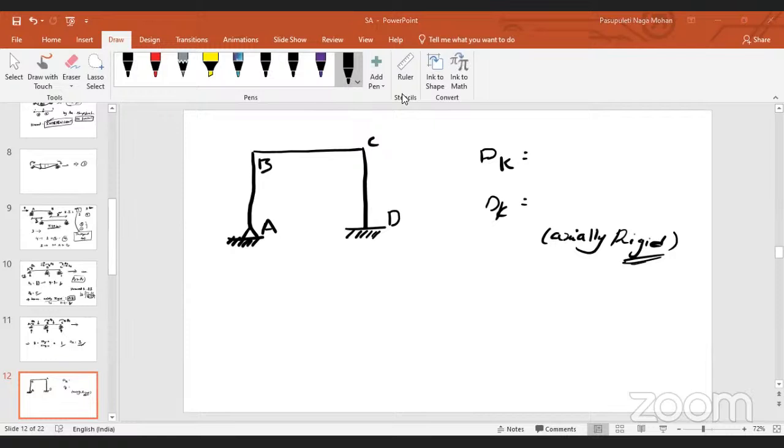Yeah, guys, sorry. Tell me, what is the kinematic indeterminacy? 1, sir. 7. Rotation at A, theta A. Kinematic indeterminacy, sir. Theta A. And any other answers? Everybody will agree with the point 1. Yes, sir, 1 only, sir. Because it has been told to be zero.